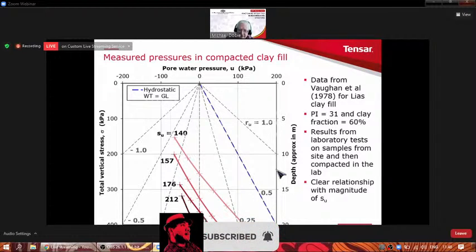So the curve is heading up. If you can imagine, if you went down to very, very small total vertical stresses, you would get very high suctions in those samples. We also see that generally, as the undrained shear strength increases at any particular total vertical stress, the pore pressure reduces.